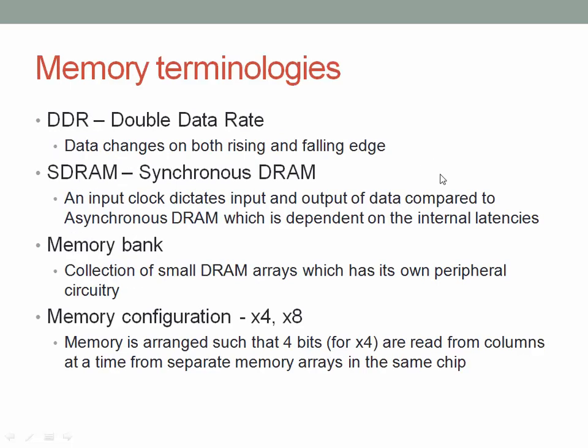So here are some memory technologies as a refresher. DDR stands for double data rate, as we all know, and so it means that the data is sent in the rising as well as falling edge of the clock. And SDRAM stands for synchronous DRAM. So in SDRAMs, data is sent with respect to the clock, so it's not asynchronous.